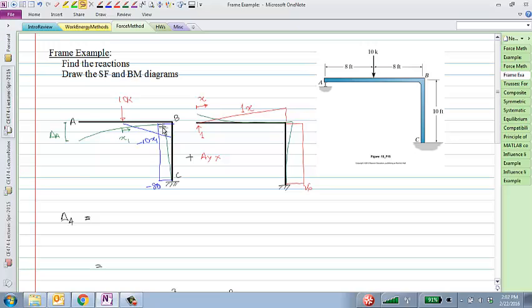That's right. So if we use the virtual work method to find the displacement at A, what I would have done would have been to apply a P prime here, correct? Instead of applying that P prime, I could just take that P prime, multiply it with a negative sign, and apply a unit load instead of P prime, because P prime at the end all does get cancelled off. So I can apply a P prime here or a unit load here. And the response of this system is really the response of the virtual system if I wanted to calculate the real displacement here. Make sense? And that's another benefit of using the force method, because you are not really doing any extra calculation by just applying this unit load here.